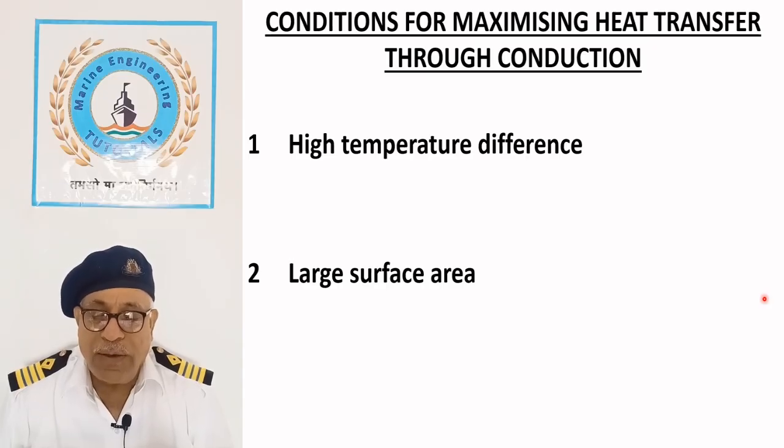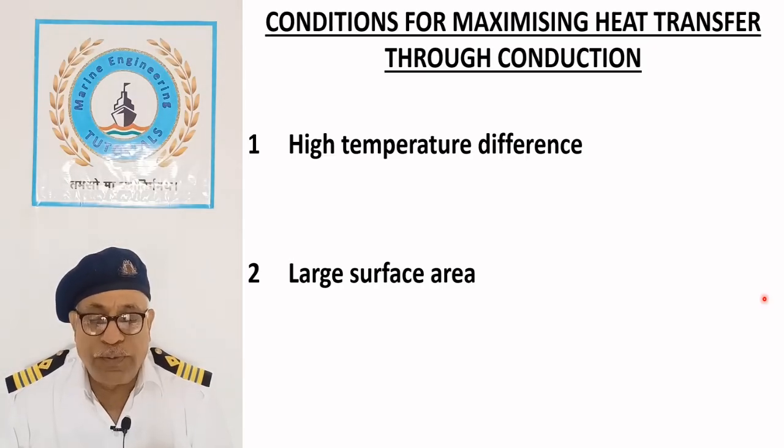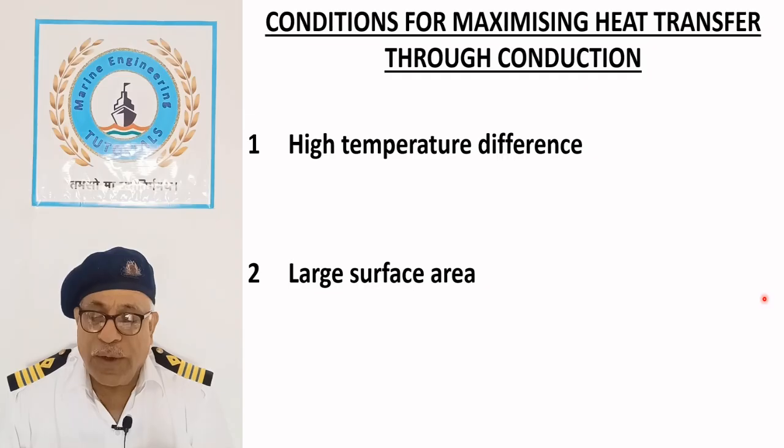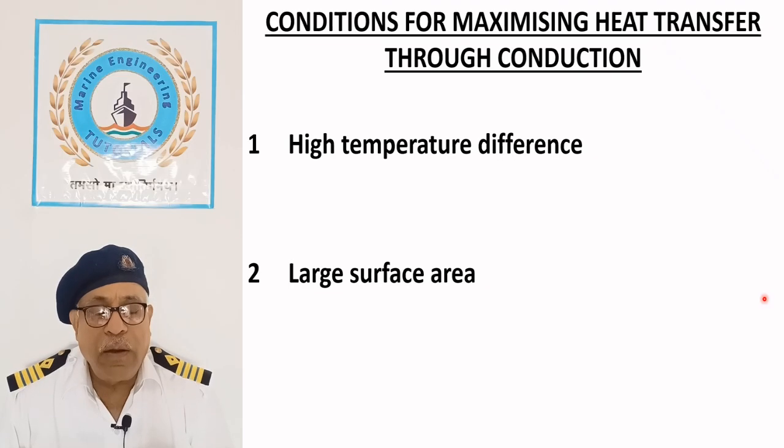However, from strength and pressure resistance perspective, circular tubes are preferred in boilers, although they provide the least surface area compared to other shapes. They offer maximum mechanical strength. Sinusoidal or corrugated tubes are sometimes used in heat exchangers to improve turbulence and heat transfer efficiency, but they are more difficult to clean and maintain.